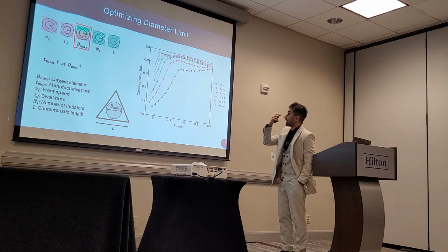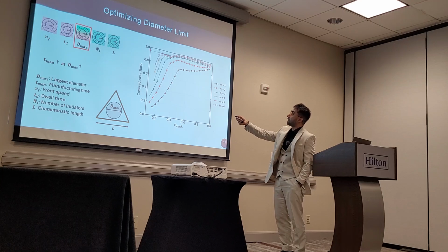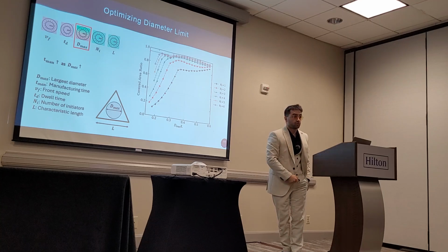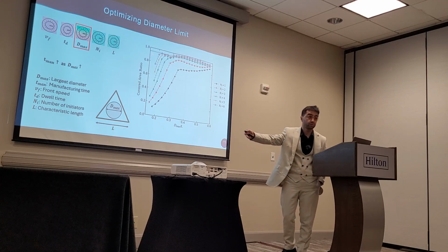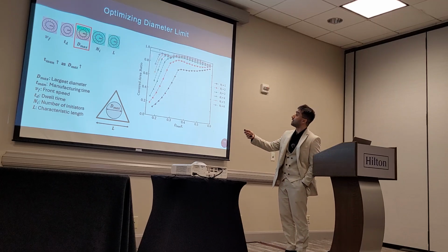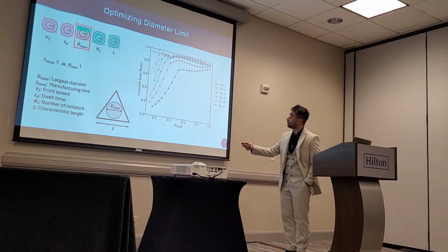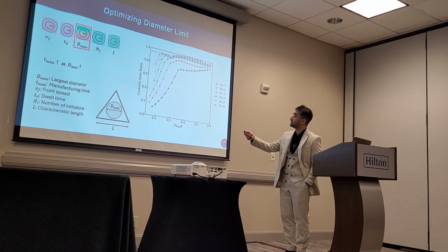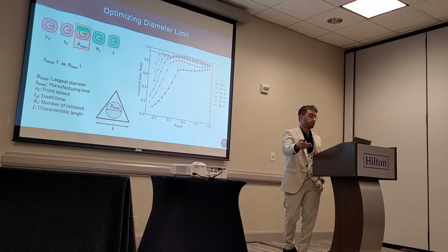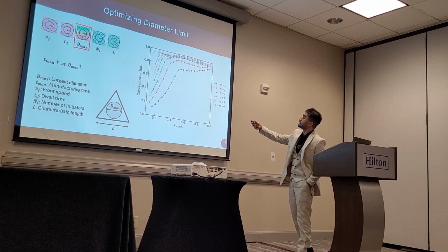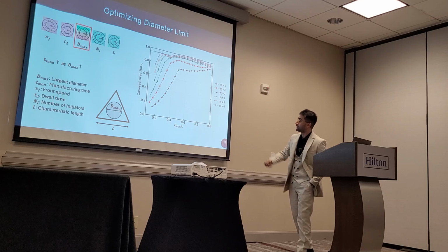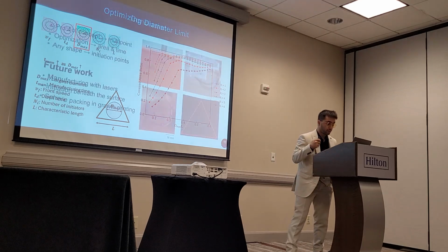So the funny thing here is that when you pick a covered area ratio, let's say 95% is sufficient for my application, the best point that you can select in this plot will be the smallest value that you can obtain for this covered area ratio, because the x-axis means the manufacturing time. On the x-axis, if it's less, it's better. And again, as I said, there will be a sweet spot for the best area coverage for D maximum. So it is good to make an optimization here.